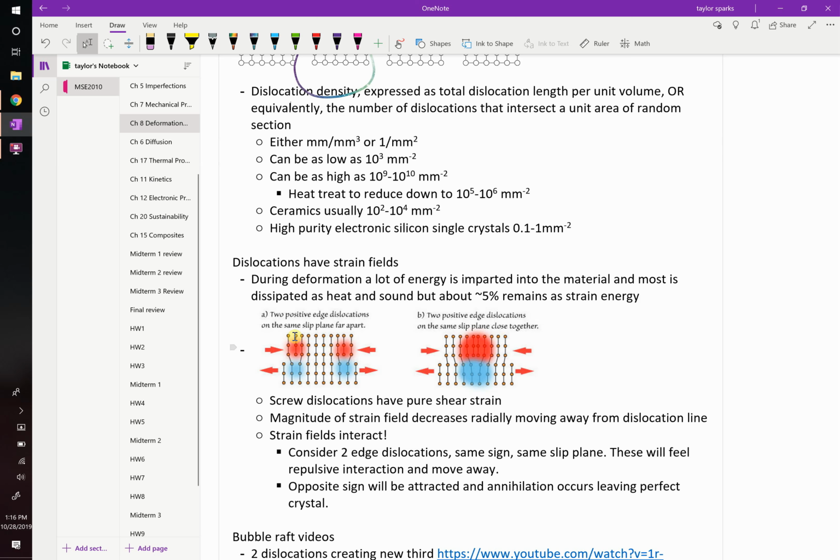And you're going to break a bunch of your dies and your bits basically trying to cut that stuff because it gets so hard. So that's what work hardening is. Blacksmiths avoid this by taking it and putting it back in the furnace. Every couple, they'll do maybe 10 hammer strokes, put it back in the furnace. This does something to the dislocation density. It can change it. It goes from maybe 1 billion back down to a smaller number. You get rid of dislocations.